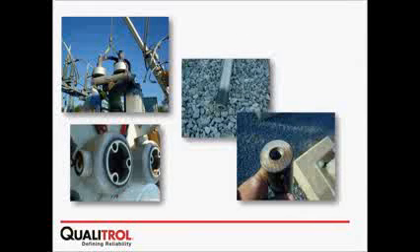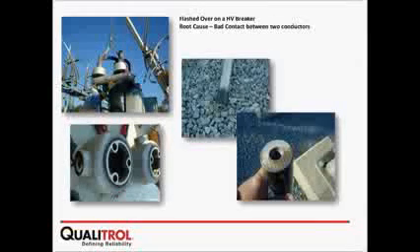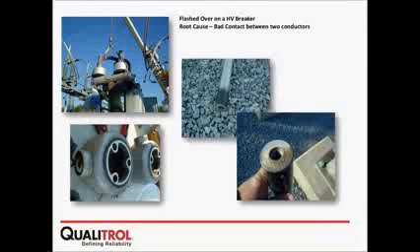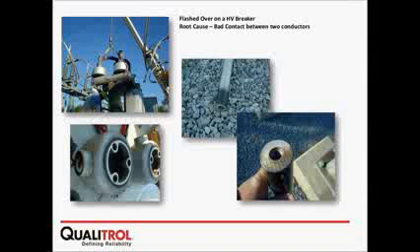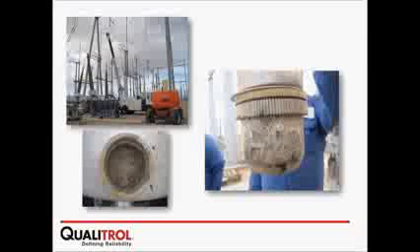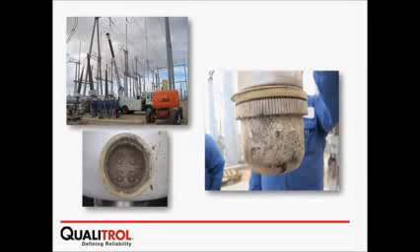In a high voltage breaker, a bad contact can cause PD, and eventually lead to a flashover as well. It can be between phase and ground. This case was between phase and ground, and it had to be replaced at the pole. This is a 500 kV, and that's one of the cases I want to show you. This was detected, and it was possible to prevent an actual flashover phase to ground.